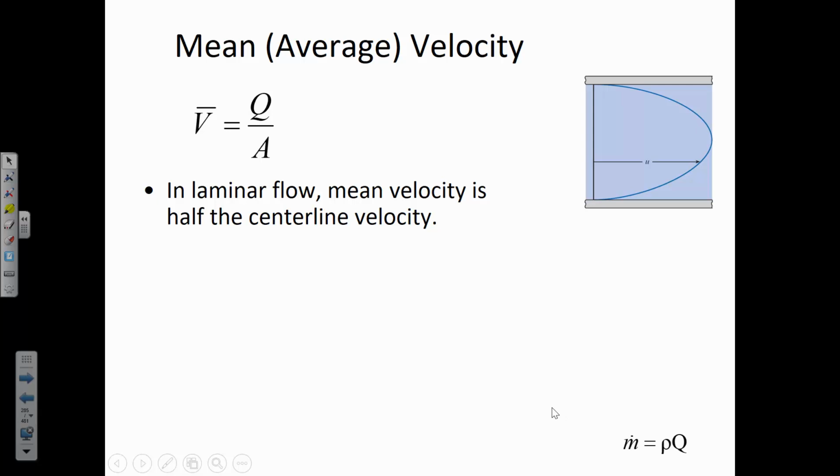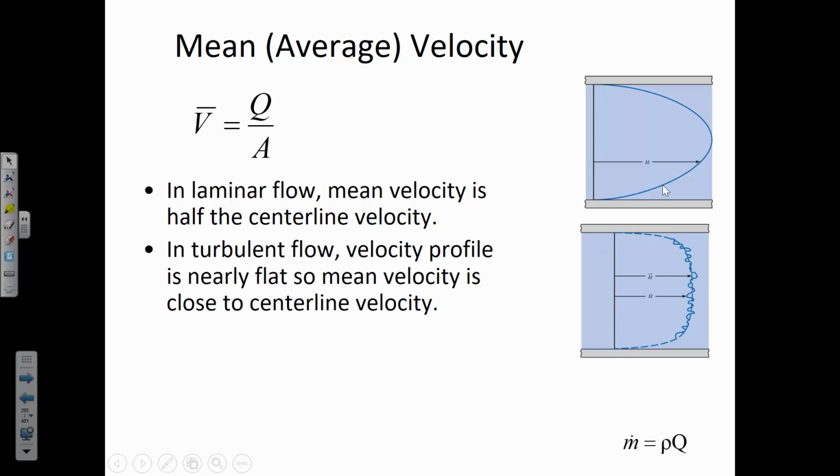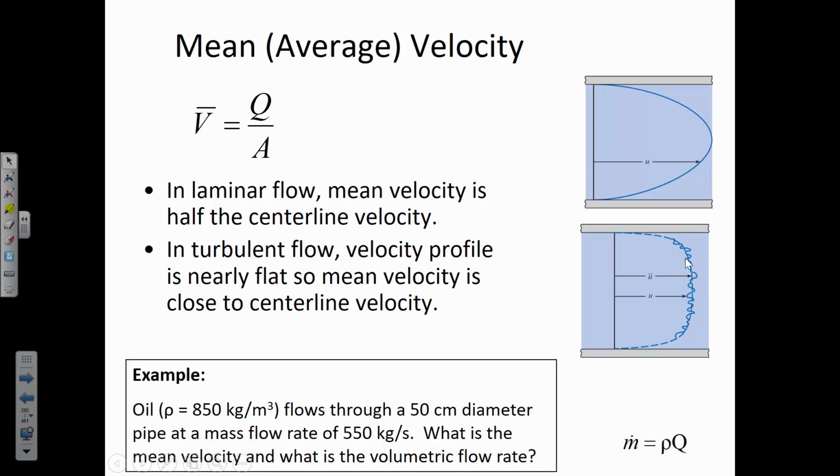Okay, so let's apply that idea of mass flow rate here, assuming that we have some average velocity, and instead of saying that there is a parabolic distribution of velocity, when you've got turbulent conditions and the flow isn't laminar, then this nice even profile gets compacted down to where there's an average velocity that's pretty close to the actual observed flow velocity for the majority of the cross section, and then as you get closer to the edges, the velocity decreases a bit.